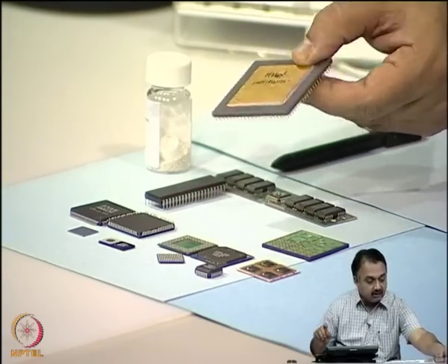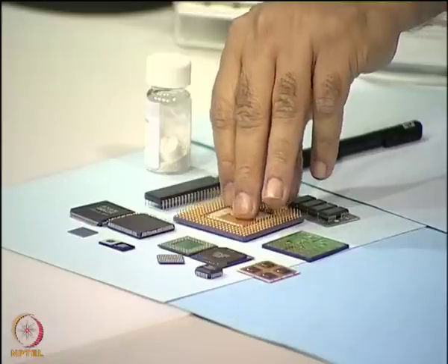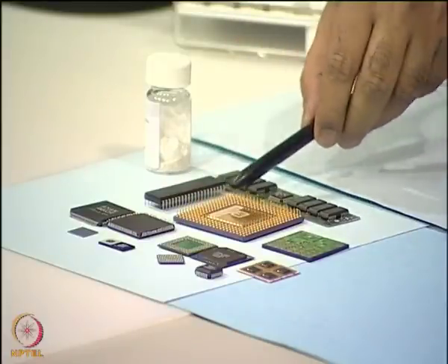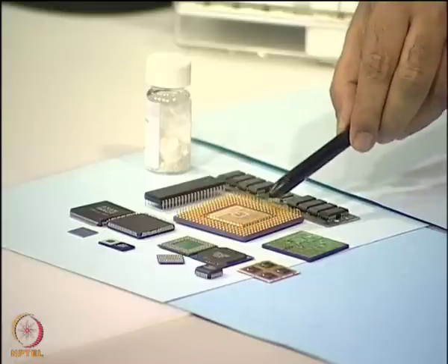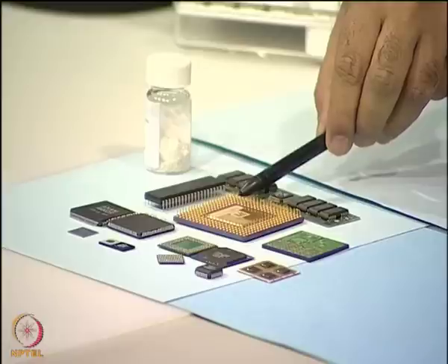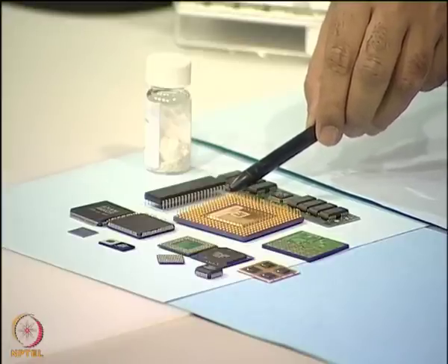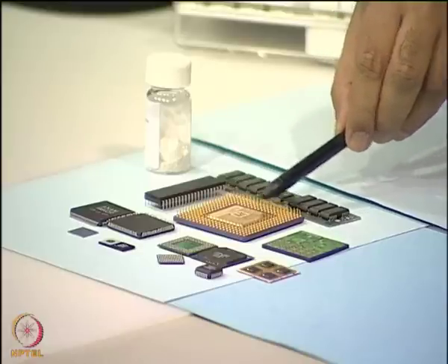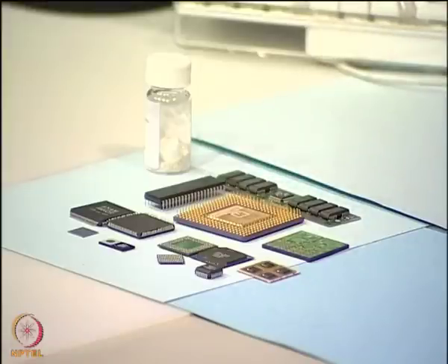This contains a metal heat sink on top, okay, and then there is a ceramic package, and on the other side you will see a matrix of gold plated pins, which are fairly long and can go into a PGA socket, typically of a motherboard for a desktop computer that was used earlier. Today we do not really get PGAs for microprocessors in desktop computing, and these are replaced by a very new technology, which we will see shortly.